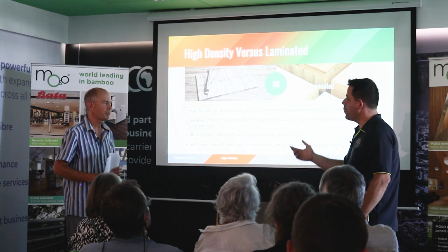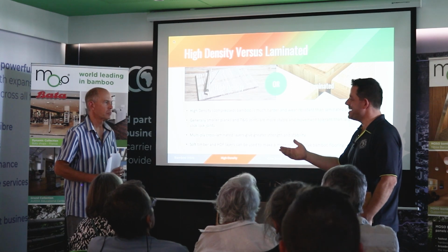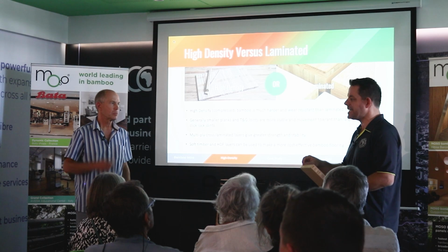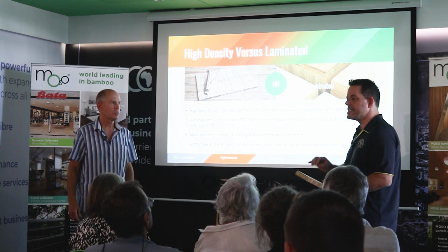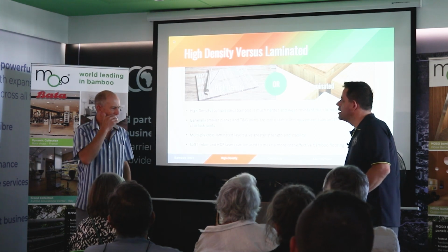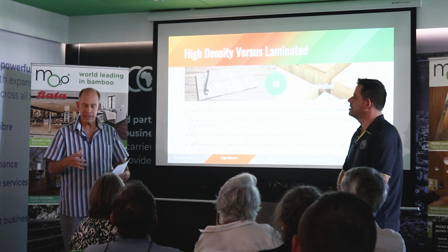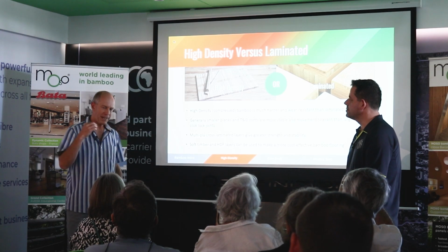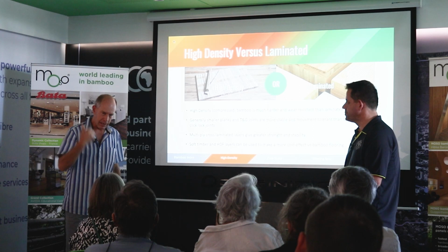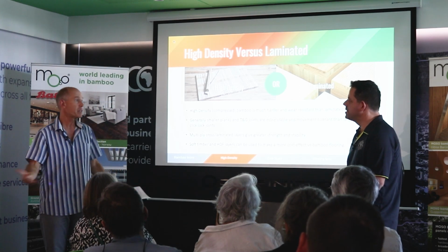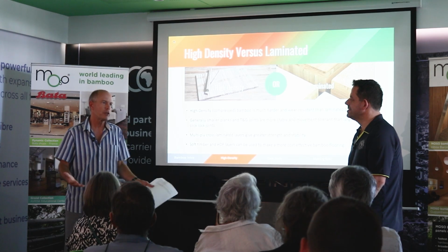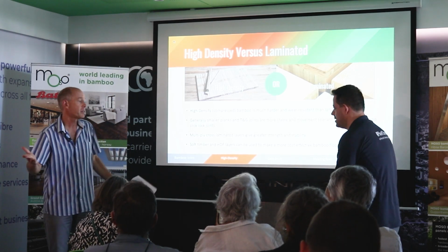That's how we make up the strand woven blocks. When it comes to the side press and the vertical horizontal, those capillary structures are still intact, so these products can still dent. That is the difference. They're very similar. In fact, bamboo strips cut from the stem have mechanical properties very similar to timber, with slightly longer fibers, about the same hardness as a medium hard timber, very similar to oak. So it can dent like oak, but you can work it and machine it, everything else.